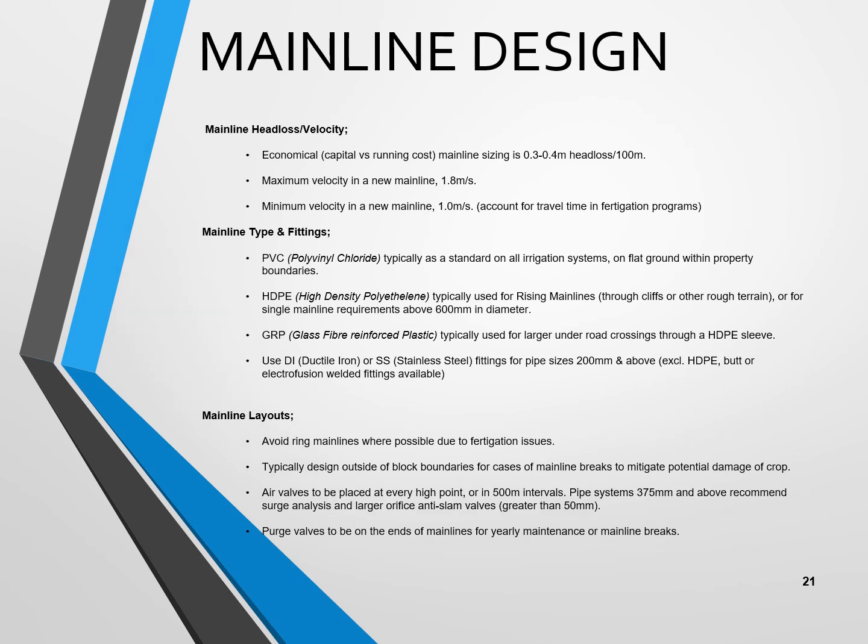When looking at mainline layouts, avoid ring mainlines where possible due to fertigation problems. I have an example to show you of this. We typically design outside of the block boundaries for cases of any mainline breaks and to mitigate potential damage of the crop.